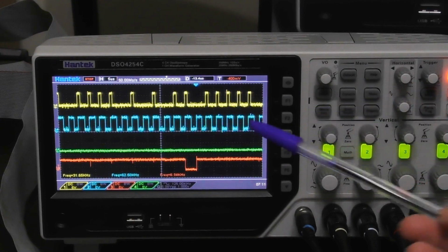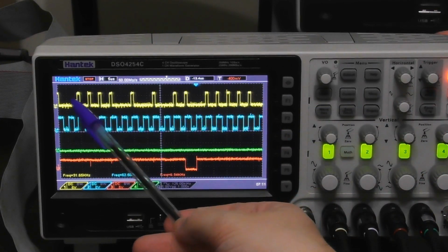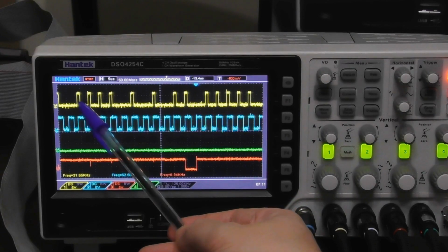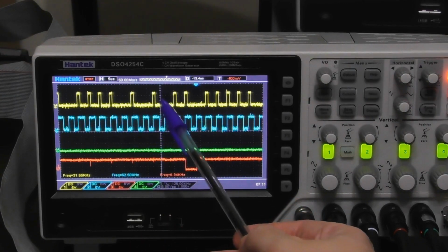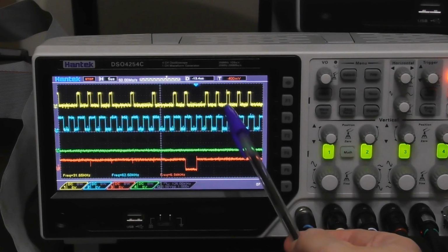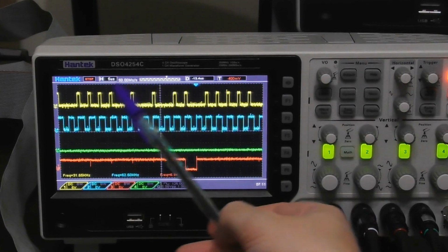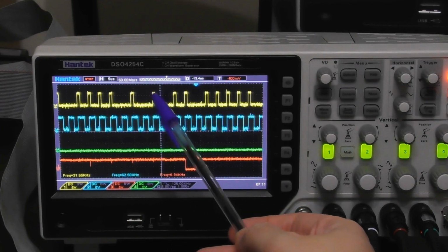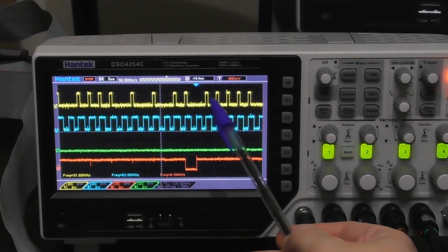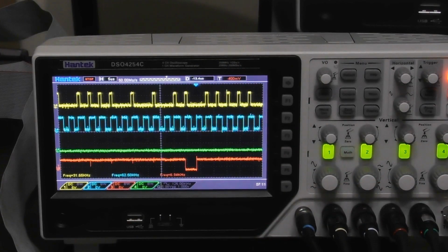Oh, there we go. So if you check the traces now, this is the clock bits. Again, we've got 1, 1, 0, 0, so that's C, and then 0, 1, 1, 1, so that's 7. And for the data bits, we've now got 1, 1, 1, 1, so that's F, and 1, 0, 1, 1, so that's B. And FB is the address mark for a data block on the disk.